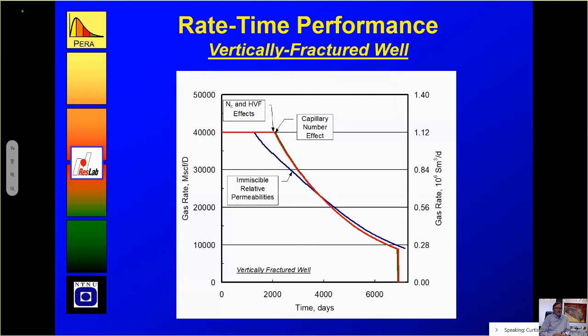I mean, if you just make a radial composite model or a hydraulic fracture model or whatever, and you lower the perm in the rock adjacent to the hydraulic fracture, 1 foot, whatever, you're saying that you get much more effect of the blockage in that case than if you have 5 millidarcy everywhere in the rock. Exactly. Okay. Yeah. No, I don't think I've ever looked at it. So I certainly think it's an important issue. If you really believe you have damage in the rock directly adjacent to the hydraulic fracture, then I would try to clean that up some way or another.